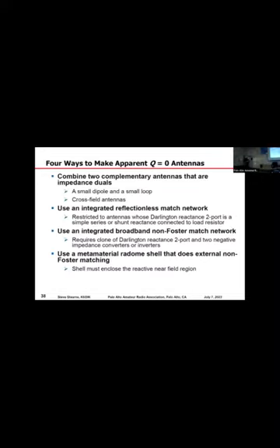We've covered the Chew bound enough so you know what it is. Let's skip this. This is technical. Now it's possible to make antennas that have a Q, but that appear to not have a Q by these formulas. So let's see how to do that. Next slide. There are 4 ways that I can think of. Maybe you can think of some others, but these are 4 ways, and some of them are classical and some are my own invention.